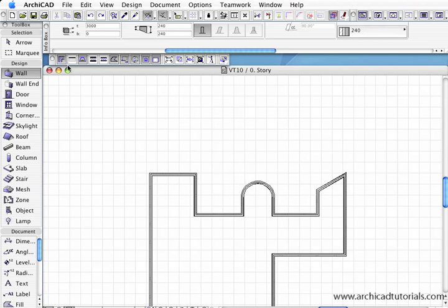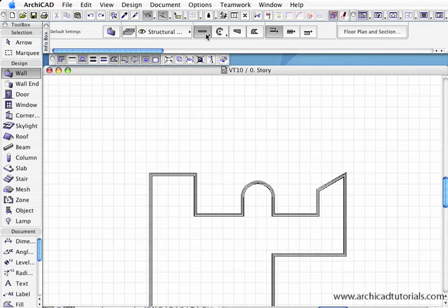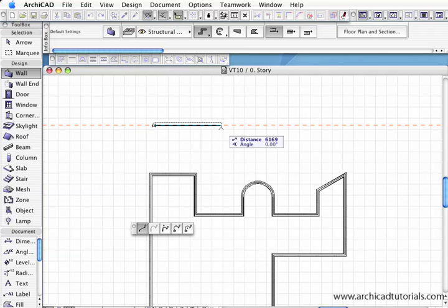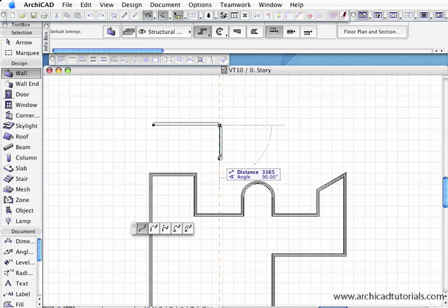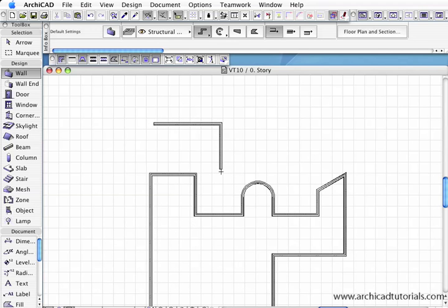Now when you're placing walls, if you choose the wall tool and choose the method, I might just use a continuous wall method here. We can use exactly the same methodology that we used when we were creating slabs. So if I left mouse click once, I drag out, once again the tracker's not on, so I click the tracker and I'll type in 6 meters, enter. I'm going to go down the page, wait to constrain to the smart guide and type in 4 meters. And if I double click or push enter again, it finishes that off.